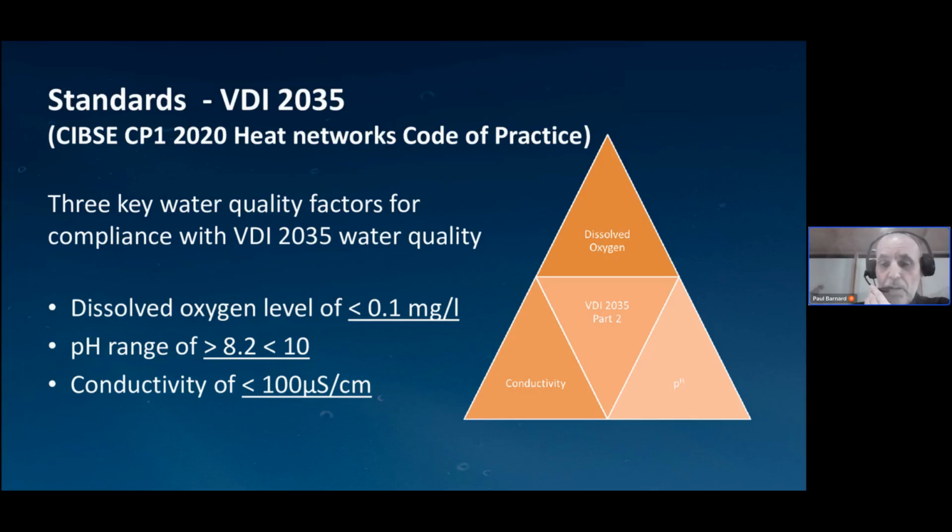We talked about how we've looked to Denmark and mainland Europe for other expertise. The Danish District Heating Association have adopted this in their approach. The Germans have. CIBSE have now written us into their heat networks code of practice as an alternative method of water treatment. And actually you'll find a lot of the HVAC manufacturers that we install onto heat networks, be it in the energy centre or in the end user's apartment, have the VDI 2035 standard as their preferred water treatment